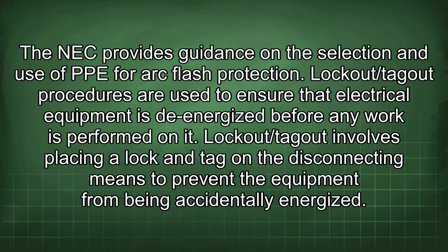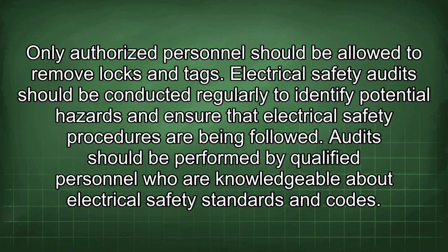Lockout/tagout procedures are used to ensure that electrical equipment is de-energized before any work is performed on it. Lockout/tagout involves placing a lock and tag on the disconnecting means to prevent the equipment from being accidentally energized. Only authorized personnel should be allowed to remove locks and tags.